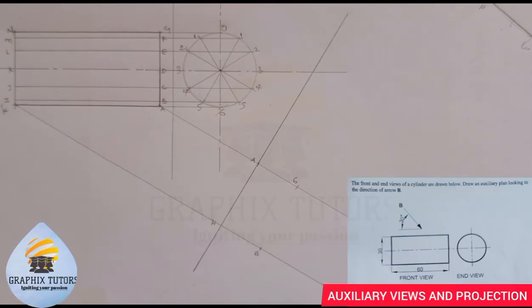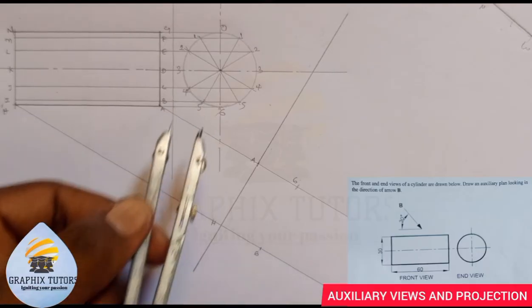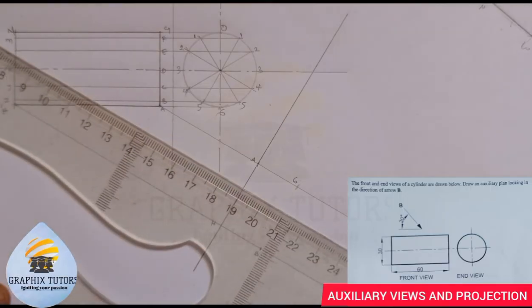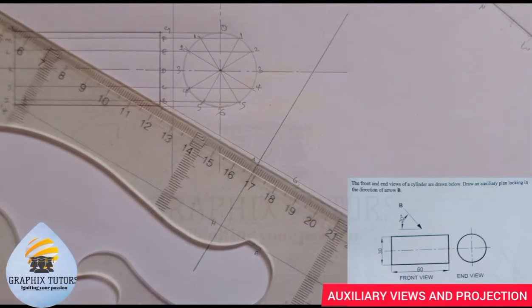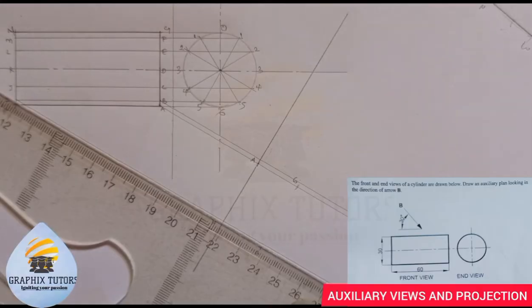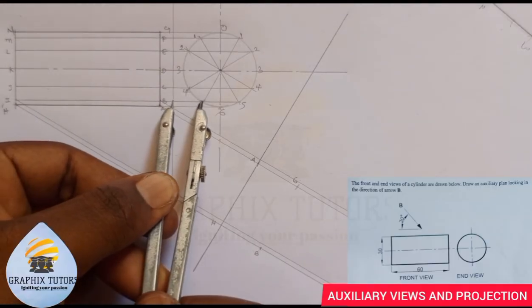I'll take the measurement again from B to 5. Can you see that? So on the line, I need to project that point first before I take my measurement. So I'll go to the line of B, point of B here, and I'll project B. I'll project B, project I too, since they're on the same line. So I'll take the measurement from this reference point to 5. Why am I using 5?